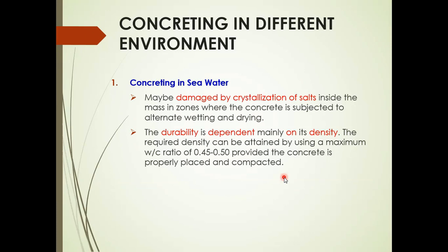Okay, so next we are going to look into concreting in different environments. For example, we are going to do some construction in seawater. Structures in seawater may be damaged by the crystallization of salt inside the concrete, in the zone where the concrete is subjected to alternate wetting and drying by the seawater.